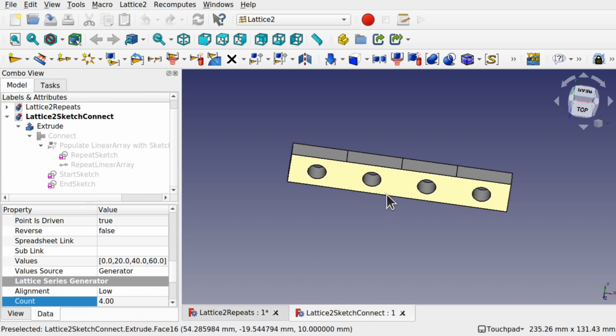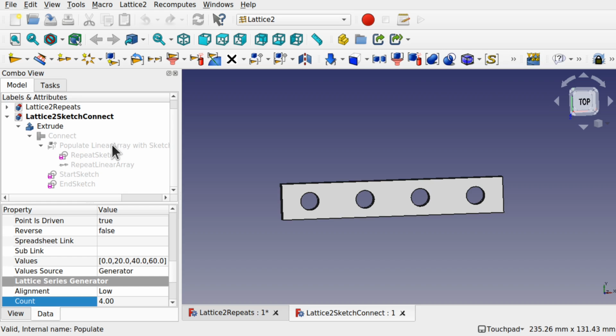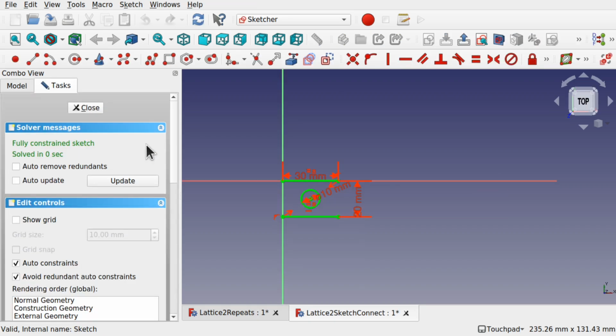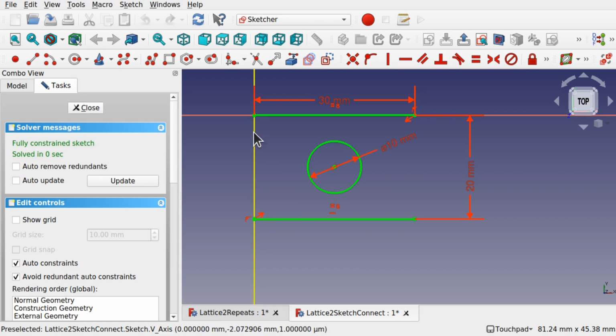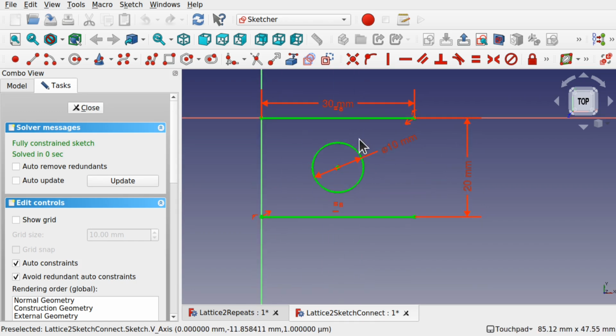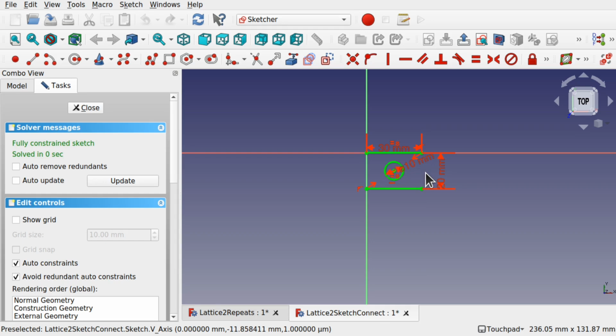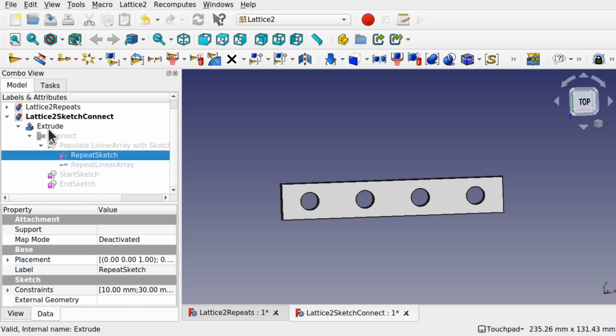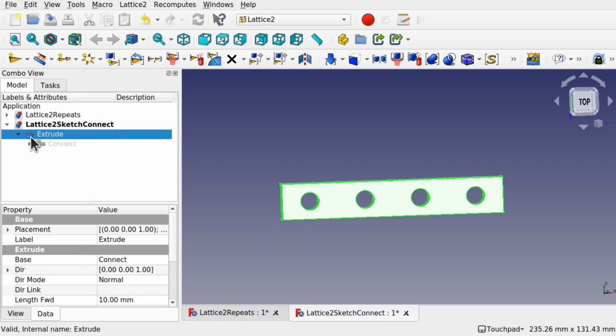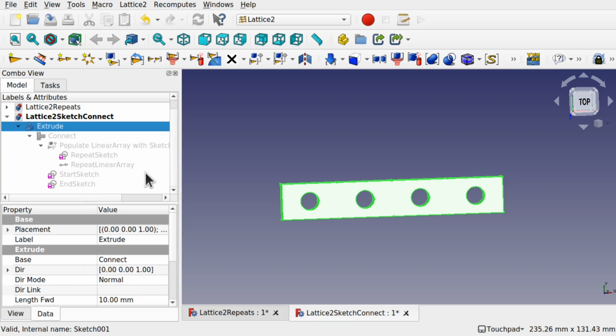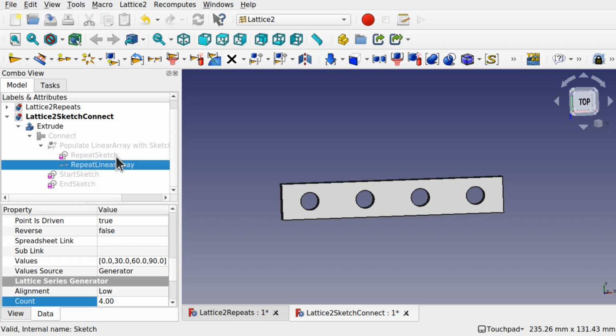This one we're actually repeating a sketch. So we've got a sketch in here that is an open sketch. We repeat this open sketch and then add formulas in there to actually close the sketch down, connect all the wires up and extrude that as one single object. So we're looking here, we can see going down the tree we've got a single extrude from all this, and we've got a number of different functions that we run on that extrude, the repeats, the connects, etc., to allow us to actually connect that all up.